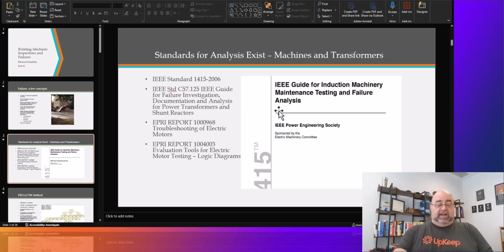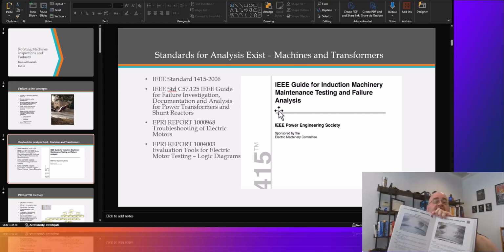So when I go through here, I can look up different types of fault issues. Let's see, one that will come into play in a minute. I can go through here and identify different kinds of conditions. So, let's just say ineffective lubrication. Here are a couple of conditions that can occur with the bearings.